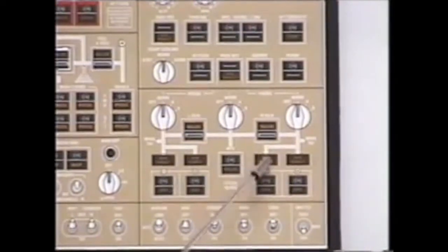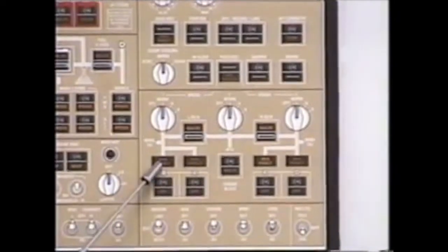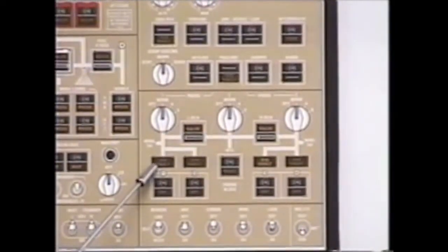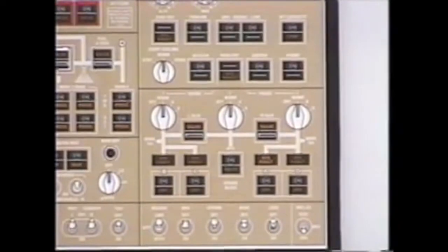Sys fault lights for your pneumatic system will come on for one of 4 reasons: high system pressure, high system temperature, if the PRV valve is open when it's commanded closed, or if the HP valve is open when it's commanded closed. If a PRV or HP valve is open, that can result in high temp and/or high pressure. It is not a valve disagreement light, because if those valves are closed when they're commanded open, you get ICAS messages, but you will not get the sys fault light, because in that condition, it cannot destroy the system.